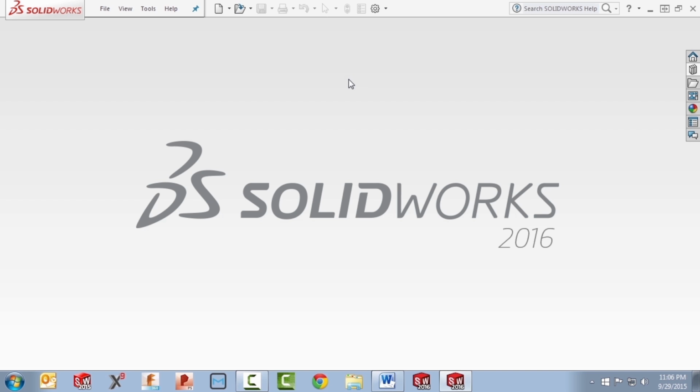What I want to focus on here when we first run SolidWorks is how you can get access to creating new documents or opening existing documents. By default, your file section will be unpinned, so you'll have to use this right arrow to go ahead and show it or hide it. I like to keep this pinned open because it doesn't take up too much space and it gives us quick access to things like creating new documents or opening recent files. You will also notice that the same icons are located to the right-hand side of this. We can create new documents or we can open existing documents from this area as well.